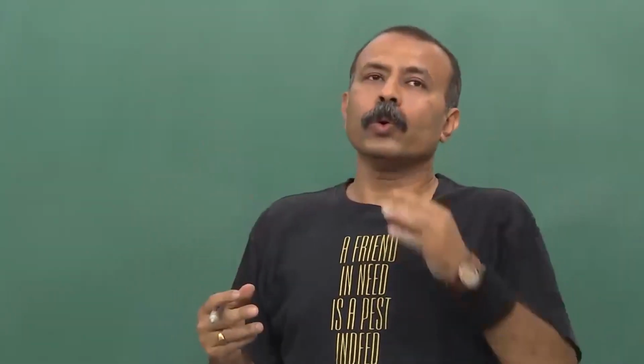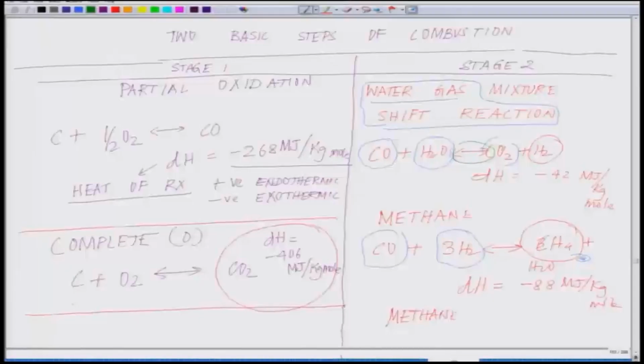So, in other words, if you see these four reactions and the parameters, say water content, if you increase the water content, there is a possibility you will have more hydrogen and CO2 forming on the right hand side. Similarly, if you could increase the carbon monoxide, automatically the reaction will shift more towards methane production, right.